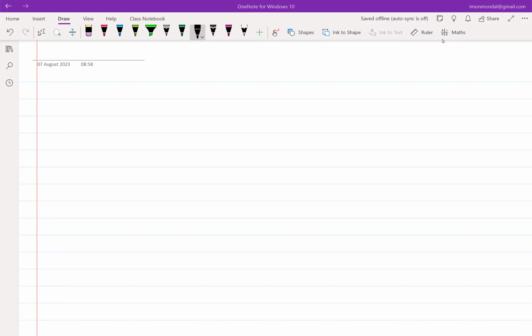Okay, so a quick recap. Essentially what we were doing in the last couple of lectures was to motivate and develop a framework for analyzing nonlinear networks. And what did we see? We saw that you can use Taylor series as a weapon to analyze nonlinear networks under the constraint that the input, or the swing across the nonlinear device, is minimal. When I say minimal, that has to be defined: it has to be smaller than whatever the other nonlinear terms are in the Taylor series expansion.